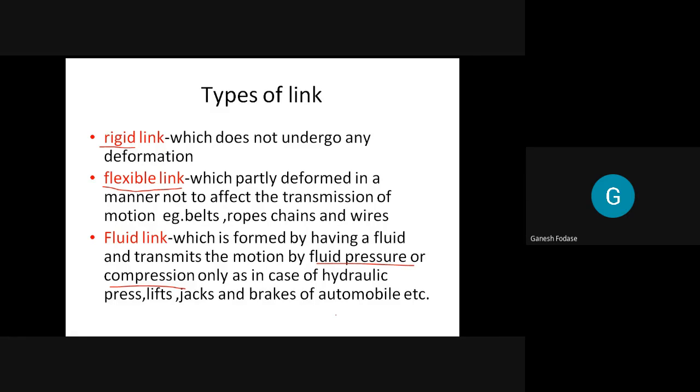Coolant may act as a fluid link. Of course, that part will act as a link in that mechanism. Even whenever there is fluid, we are transferring, in all these cases we discussed, hydraulic press, lifts, that fluid portion will act as a link, because it is transmitting motion from one part to another part.